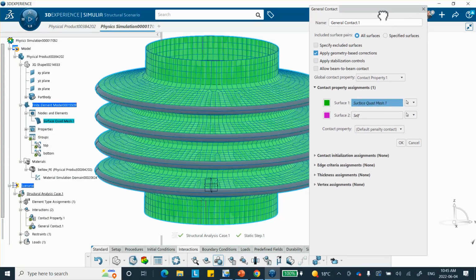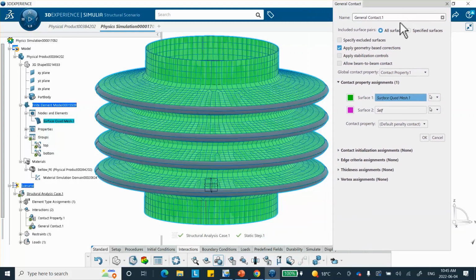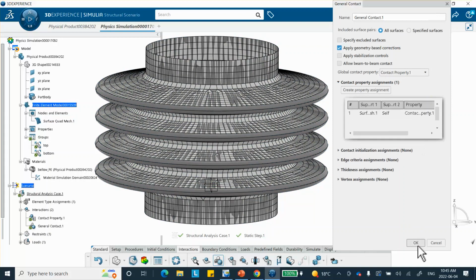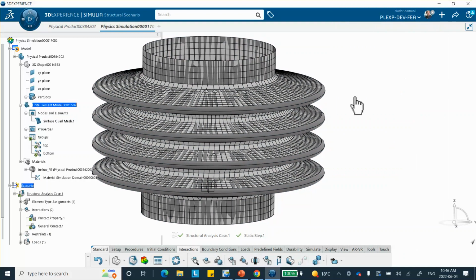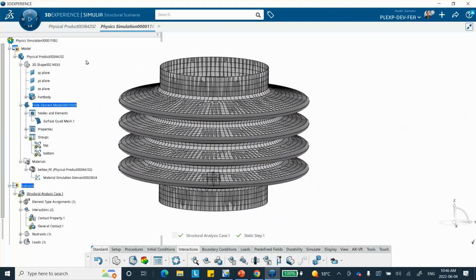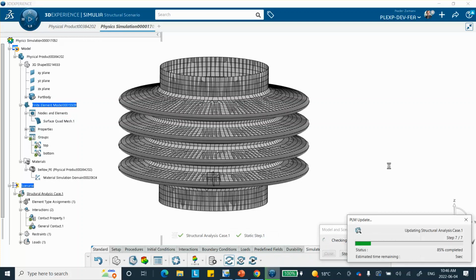See where is the okay? I'll be able to close this. Oh, okay, right there. And of course, it's the default stuff there. Oh, contact property 1, okay? I would have expected, because it's done here, that it would not be necessary, but it looks like it is. And we say okay. And we say okay. And hopefully everything that we want is done. And now we're going to go to the simulation tab, do a quick model check here. And I'm sure it's going to go through.